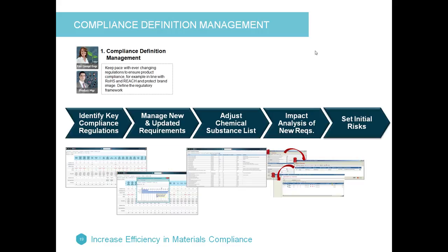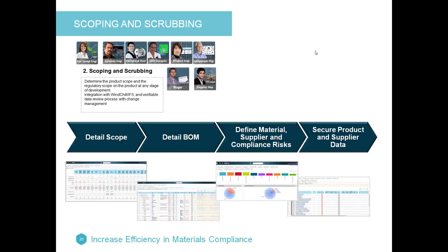You also need to look at the risk. The risk analysis, something I just mentioned, is actually required when you're looking into the RoHS recast if you are following the EN 50581 standard, that you're required to do that. But it also is important for you to prioritize your work. It's quite extensive work when you start out finding the material declaration information, so it's good to start in the right end.